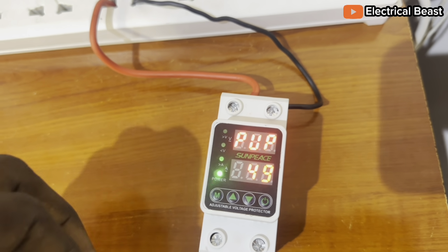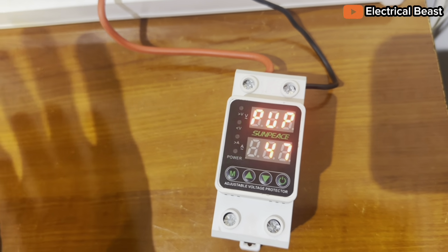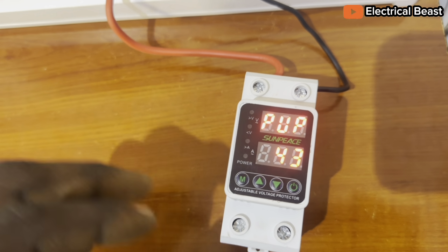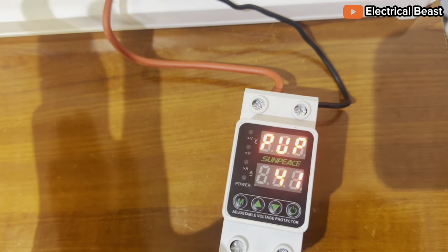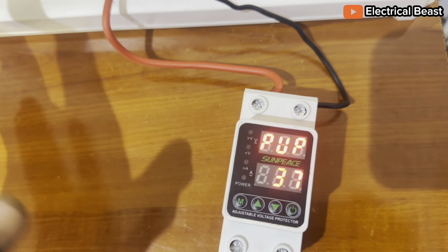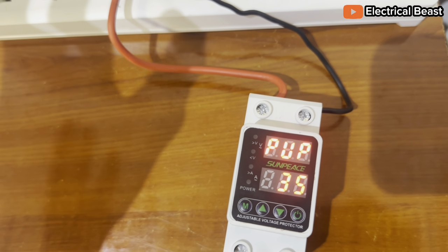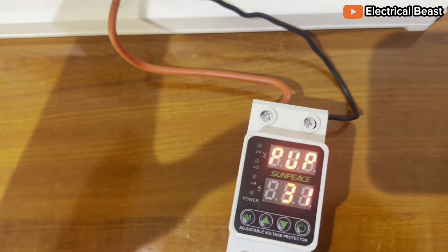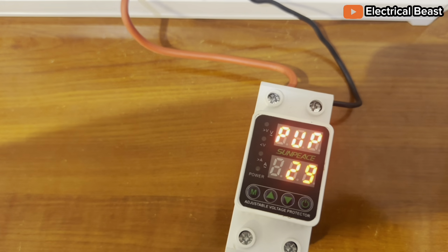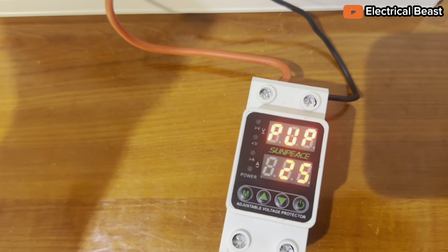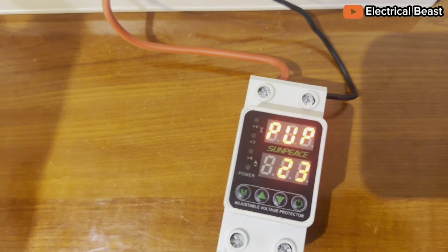Power up time 57, 56, 55 is delay mode. So this thing is very important both for your input and for your output. If you have the mains, just try to make sure everything is complete: your voltage protectors, both input and output, surge protectors, input DC and AC, then your input breakers, output breakers, solar DC breaker, then your battery breaker, and make sure everything is well earthed to the ground using an earth bar.